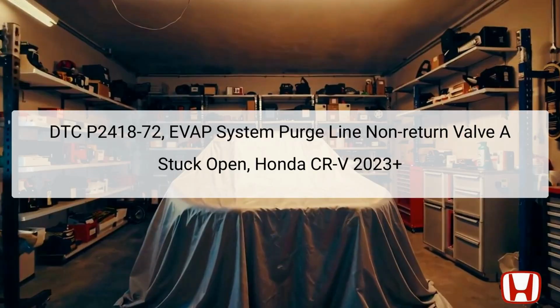DTC P2418-72 refers specifically to an issue within the evaporative emission control system of the Honda CR-V models from 2023 onward. This diagnostic trouble code indicates that the purge line non-return valve A is stuck in the open position.